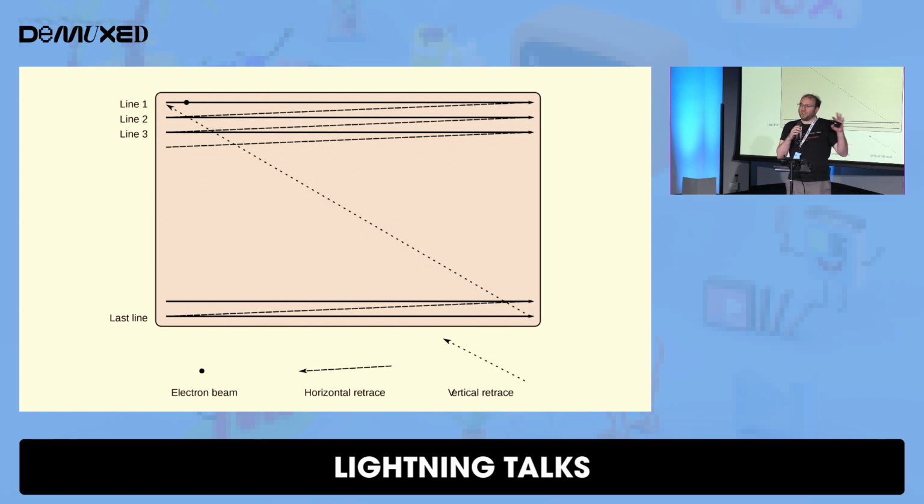So instead, all of our geometry controls, all picture controls are mostly done with deflection. Effectively, we have to have our own model of where we are in the raster, and we have to compare it to the video signal coming in, and we move ourselves to match. And the timing here has to be very precise. It's very similar to the clock recovery talks of earlier, but now we have to be accurate down to sub-pixel levels, because if we have any less accuracy, you'll see the picture jitter left or right.